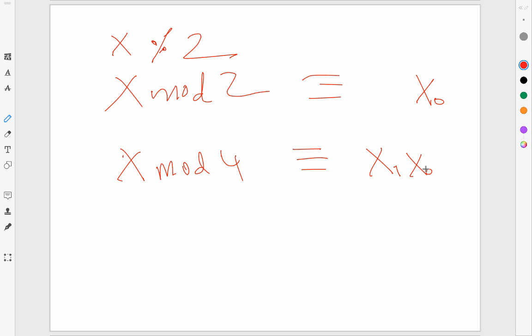Question 2, I don't think anything significant came up there. Question 3 is the decoder question, where you are given 2 to 4 and 3 to 8 decoders, and then you have to make a 7 to 128 decoder. The thing to realize is that I have 7 bits to decode, and I could obviously create a 7 to 128 decoder just using gates, but the question prohibits it. It requires you to use two decoders.